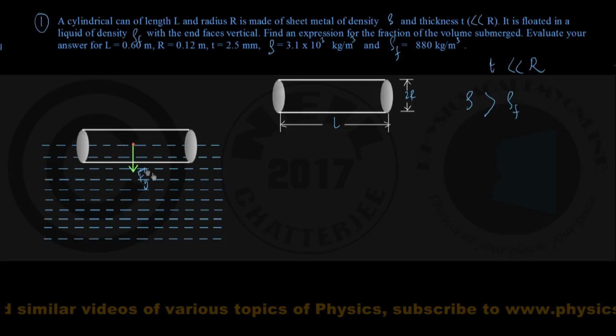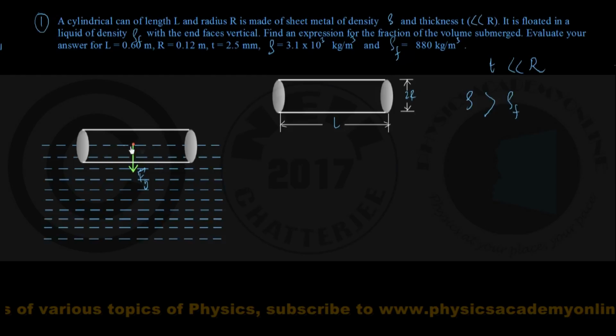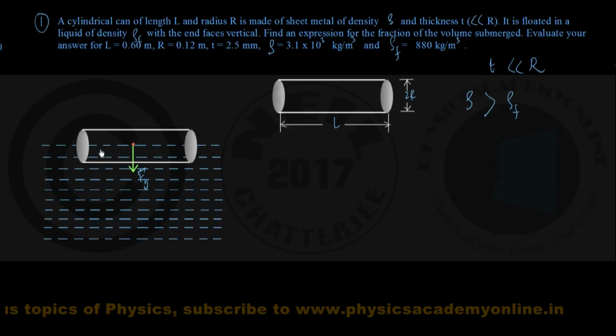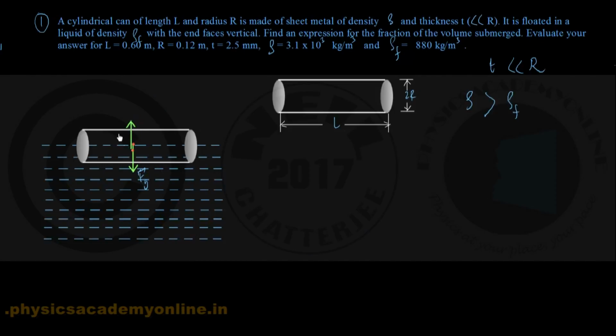And the center of buoyancy is the point that is the center of gravity of the displaced liquid. Since this part of the cylinder is taken to be immersed, that is also the location of the displaced liquid before displacement. So for that displaced liquid, the center of gravity is somewhere a little below the CG of the entire can, and therefore the center of buoyancy is also this point, through which the buoyant force is acting vertically upwards.